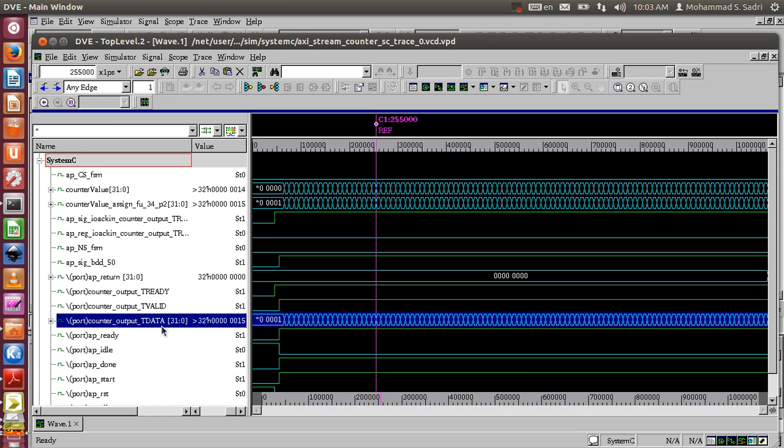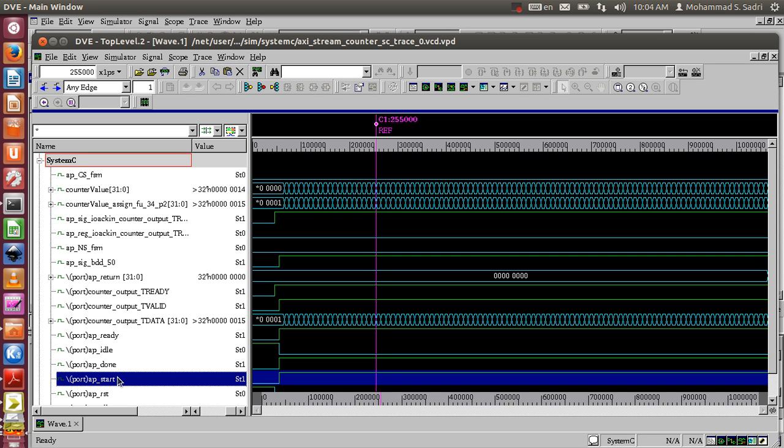And this is a kind of art of Vivado HLS. It generates for you all of the unnecessary, I would say, less important interface signals. So as you see, for example, it is also driving automatically for you the IP underline start, which is the signal which controls the enable disable operation of your module. So it really facilitates your simulation and verification task.